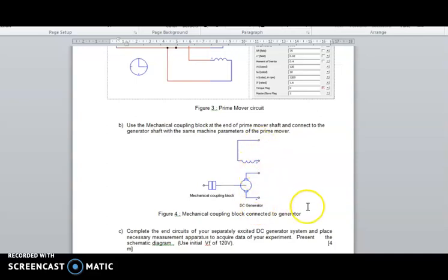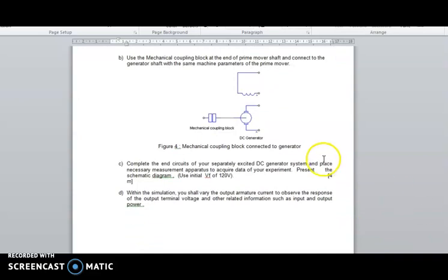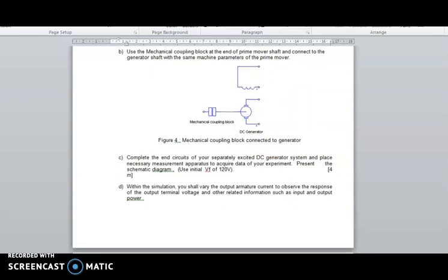And so this DC generator will be connected in separately excited. So this RF here has its own voltage terminal. Your output terminal here will be connected to your load. So the load just uses the same concept as our previous lab, which is connected into your simple resistance. So you will control the current by using Ohm's law, which defines what kind of voltage, what kind of current you want to set. So what kind of resistance you have to put into the circuit.